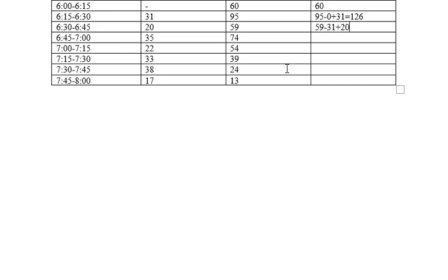Okay, so 59 vehicles departed and there was a queue of 31 vehicles. Okay, so 59 minus 31, so whatever the number you get, these are the vehicles which have arrived, plus some of them, the vehicles which arrived, may have been left in the queue, so that's why plus 20, the present queue value. Okay, so this gives me